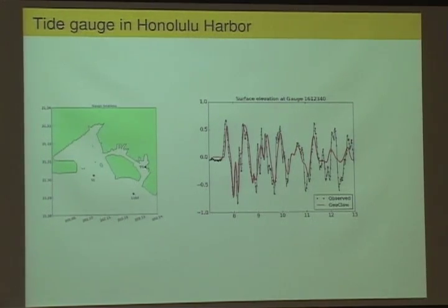The shallow water equations do quite a good job, but there was still quite a bit of question about whether currents would be modeled as well. So we also looked at one of these current gauges out here. At this point, there was actual observations taken. We put in a synthetic current gauge here just to show that the current gauges have a lot more variation from one location to the next than the depth does.